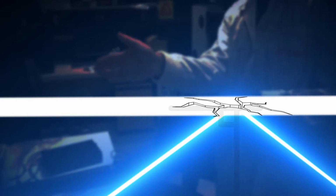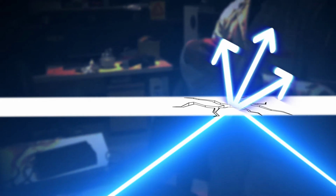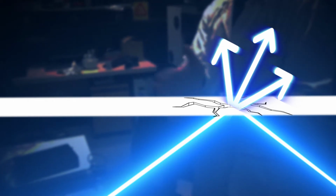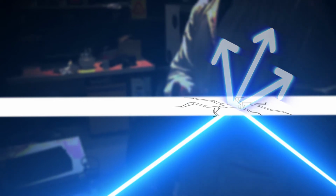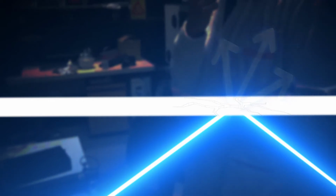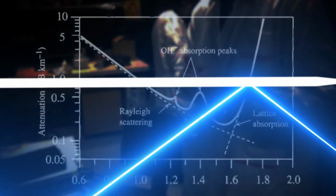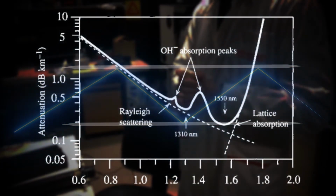If the surface isn't perfect, the normal will change in the region of the defect, which leads to a different reflection angle. From that point on, if the rest of the fiber isn't perfect, the light can travel with an angle inferior to the critical angle, leading to part of the light being reflected but the other part being transmitted. This means that the Mie scattering can result in the loss of the amount of light, less signal's intensity. The light scattering contributes to the signal's attenuation, either the Mie or the Rayleigh.